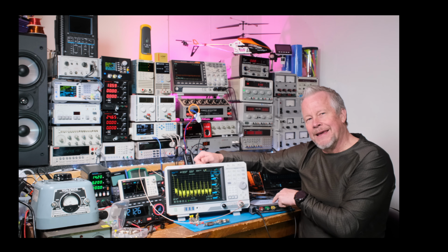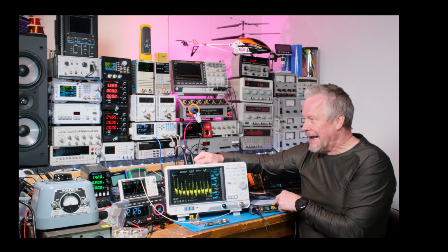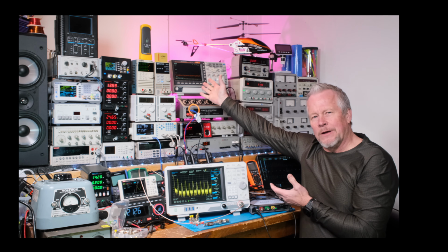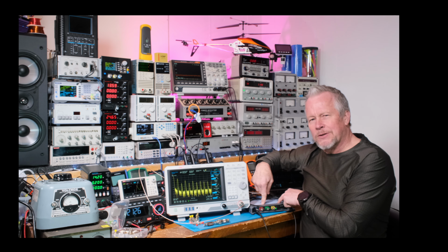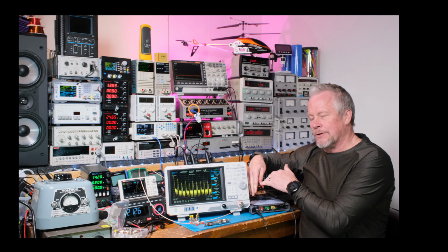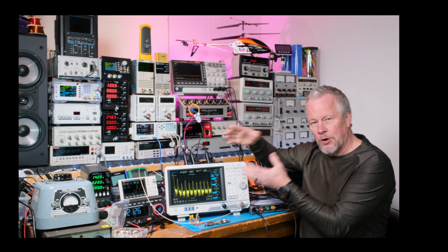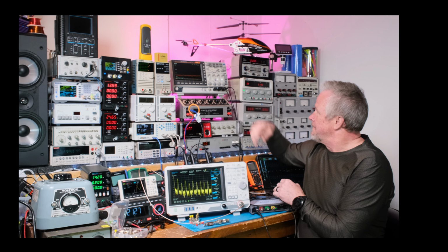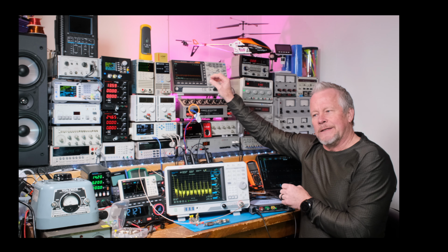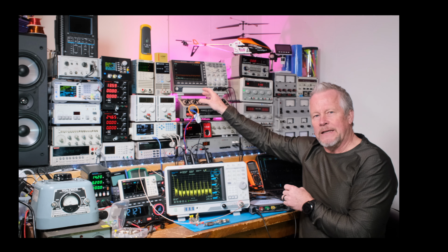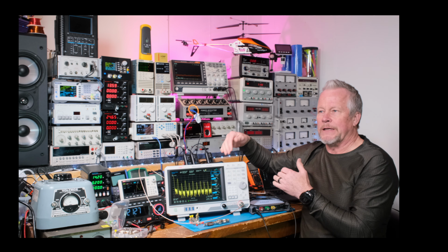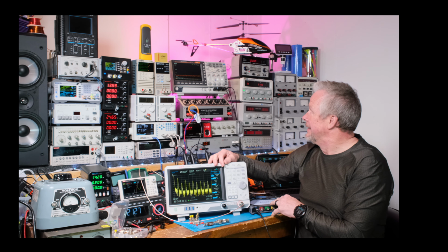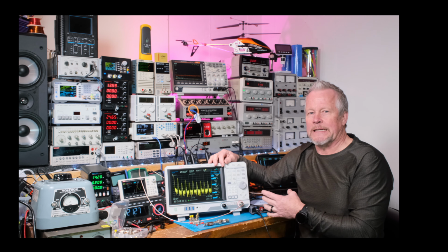So what I want to do is just do a real quick video today using the PicoScope. The PicoScope's pretty unique. It has a way where, like my GWN stick up there, it can do what's called an MDO, mixed domain. This PicoScope is called an MSO, mixed signal, meaning it goes from time domain, scope type stuff, to logic analyzer. So it does two different domains. The MDO does two different domains too. It does an oscilloscope, time-based, and it does FFT, like a spectrum. It's supposed to be more like a spectrum analyzer than an FFT. Now, the thing is, it's not really a spectrum analyzer, even though it looks and feels like one.